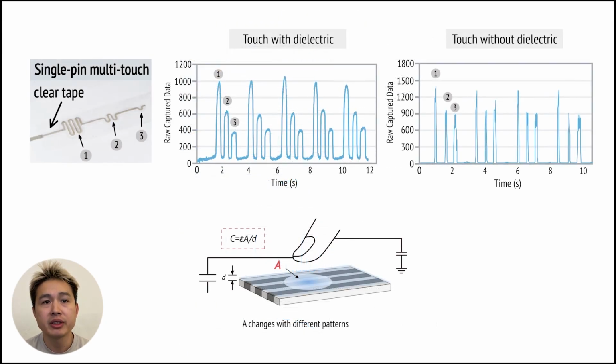While most capacitive sensing scenarios involve direct contact with the electrodes, we have also experimented with adding a dielectric layer on top of the silver trace, such as Scotch tape or dielectric ink, to form an additional capacitor between the trace and the user's skin.